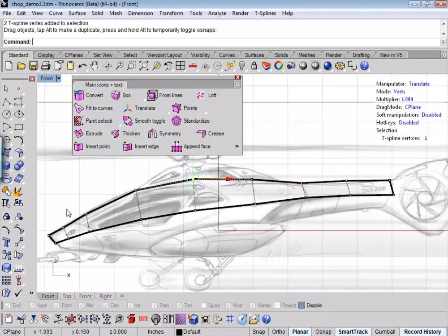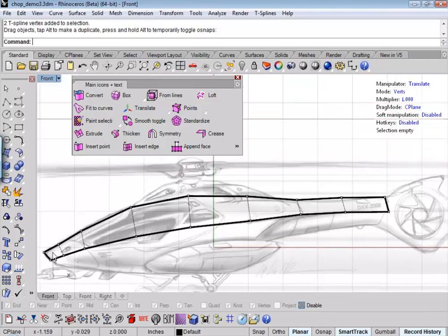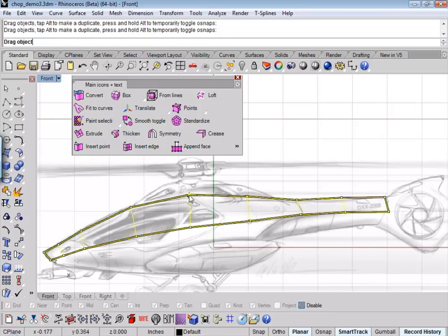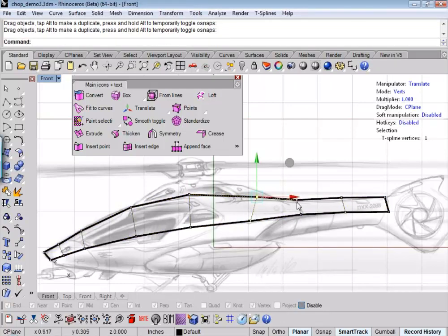T-splines essentially is an exercise in interpolation, and so these points are going to be interpolated smoothly when we go from box mode to smooth mode, and allow T-splines to then calculate the smooth surface between this. So we're creating the anchor points for where this is going to get interpolated through. If there's going to be a break here, this is your high point, it would make sense to have your high point in box mode be somewhere near where you want that to go. If there's a transition here, it would make sense for your patch layout to follow that in a logical manner.